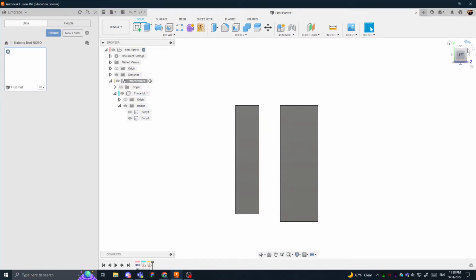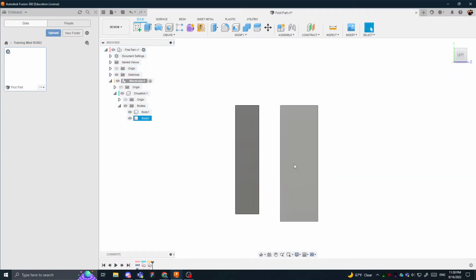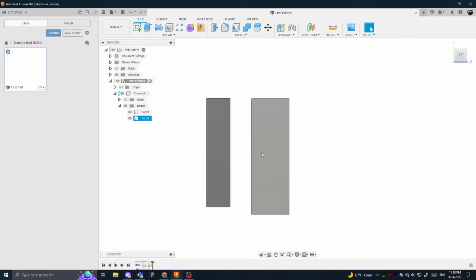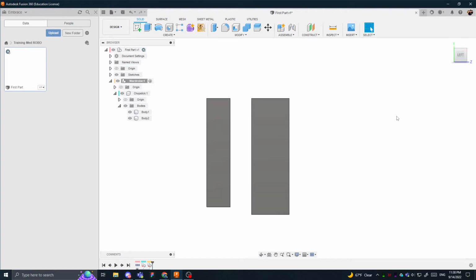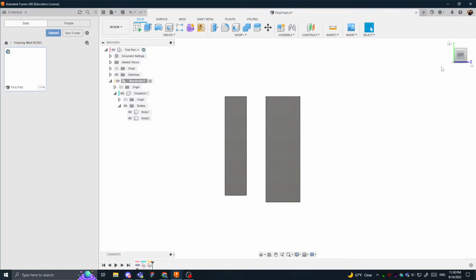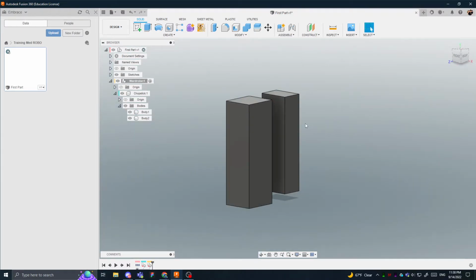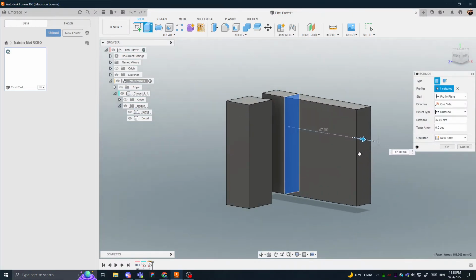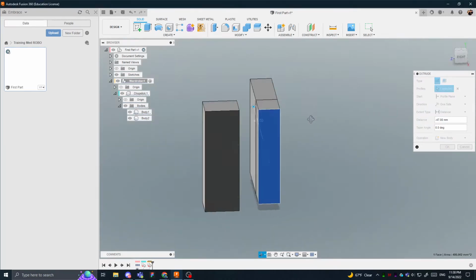You can click on the view cube to orient yourself to a corner. This is usually called isometric view. This is an orthographic view because it's orthogonal, so perpendicular to the viewpoint. You can flip to the top and stuff like that. XYZs are labeled, so if I want to extrude in the positive direction, like if I want to pull this block thicker, notice it's a positive number in the X direction. So if I type in a negative number, it goes in the opposite direction.